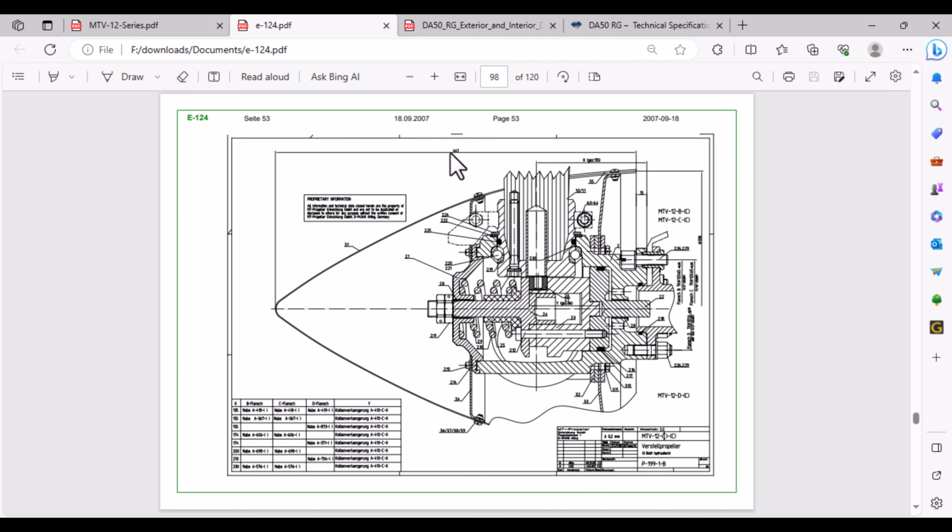Now, if you watched the previous episode, at the end, I asked you guys to install this software, JavaProp. It's actually just a Java coding. So basically, we need the blade element theory for us to design the surface of the propeller, because there are a lot of dynamics involved which are interdisciplinary. You know, they are intercrossed, and it's a long process to calculate all those cross sections and to be able to identify the pitch at every single section. So this is a simplified way for us to be able to determine that. And it's very easy to install, very easy to use. So just go ahead and open JavaProp.